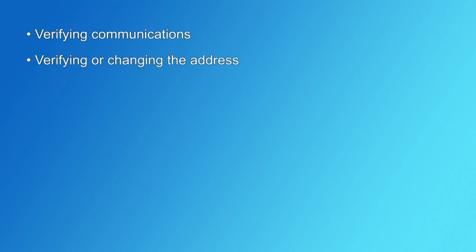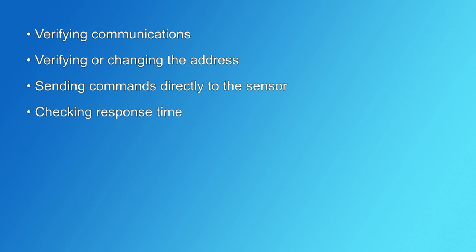In this video, we'll show you how to communicate with an SDI-12 sensor using a terminal emulator. This is also sometimes called the talk-through mode, as you'll be communicating with an SDI-12 sensor through the data logger it's connected to. Some of the reasons you may need to communicate directly with an SDI-12 sensor include verifying communications, verifying or changing the address, sending commands directly to the sensor, checking the response time, and troubleshooting.